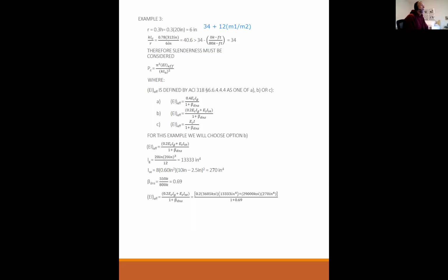Yes, thank you. Okay. So that's what I'm saying: when you sum up the moment of inertia for the steel, the parallel axis portion of it, A D squared, is really the only part that has any significance. If you look at number 7's moment of inertia about its own axis, it's a fraction of an inch to the 4th. So we neglect that. Okay, thank you. Okay. So that plugs in right here.